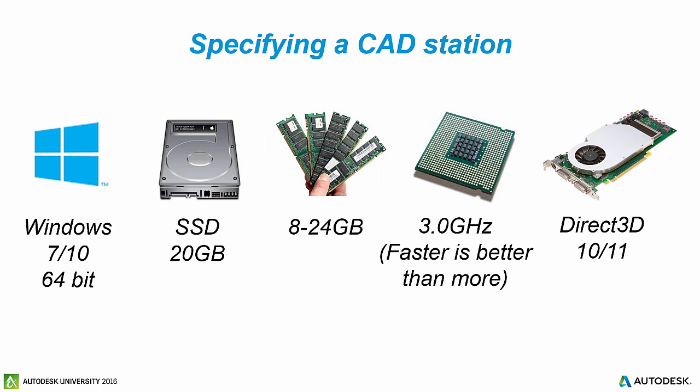So you can take your graphics card details, go to the Autodesk site and look for the recommended driver, or you may even go to your driver's own software download site and see if they've got a recommended driver for your software. If they have one, use that, because that's going to be tweaked to suit your software. It's going to run much better.